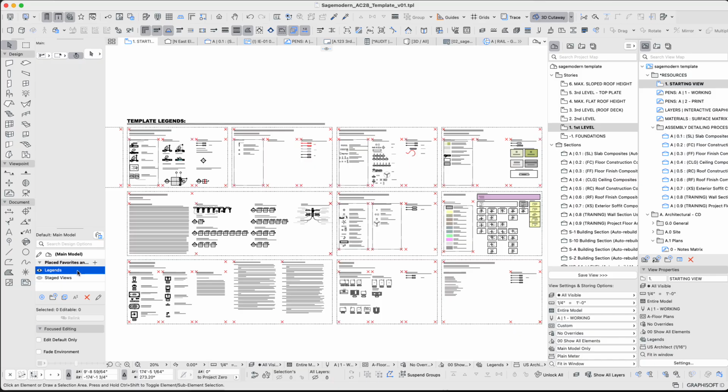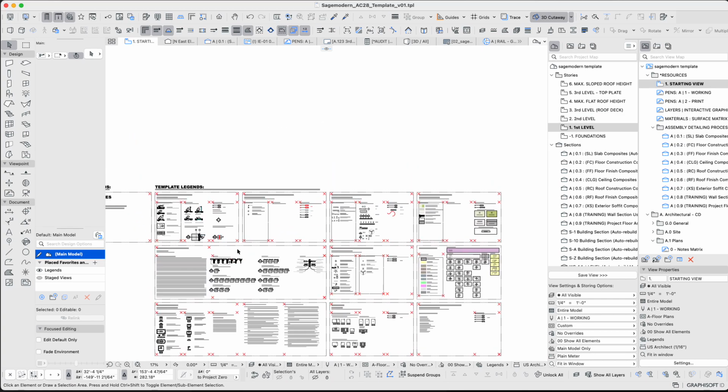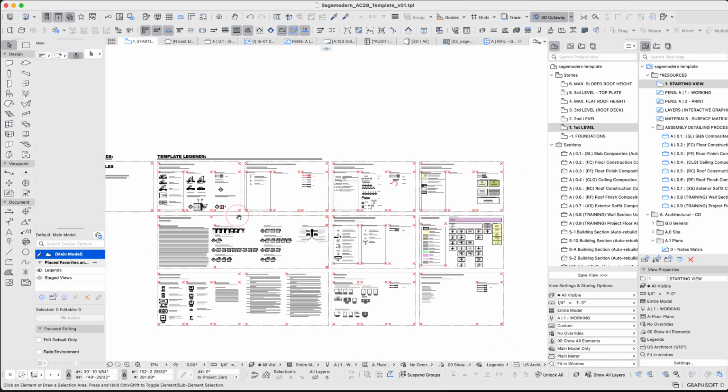It's on a design option because I've filtered all the schedules to eliminate anything that is not in the main model. So anything that lives here will not show up in a schedule. But you can use it to drag and copy, put it into your project, and then link it to the main model when you're ready.